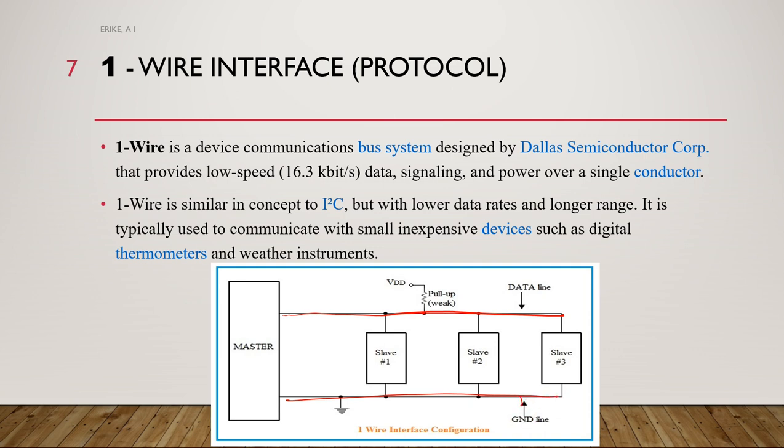Okay, so to accomplish the communication here, the one-wire device will include an 800 picofarad capacitor to actually store charge and to power the device during the periods when the data line is active. There's always one master in overall charge, which may be a PC or a microcontroller.